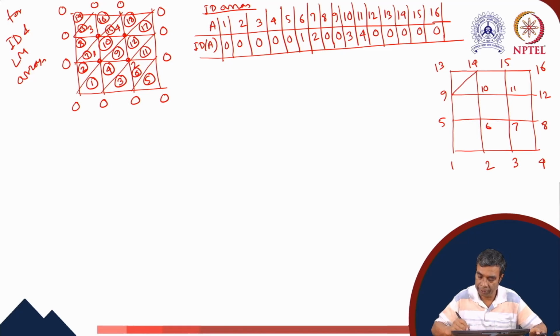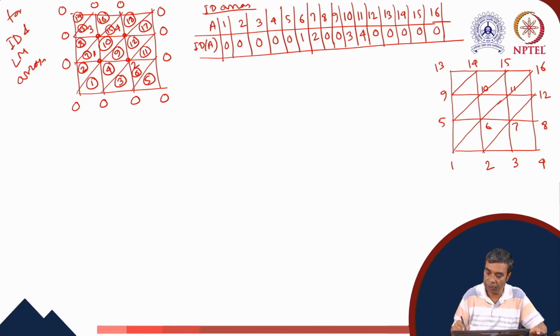Here we generate the finite elements. We can cross check that at global nodes 6 and 7 our equation numbers are 1 and 2, and at global nodes 10 and 11 our equation numbers are 3 and 4.